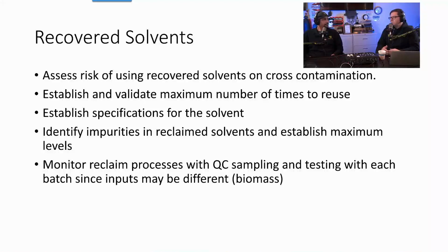The solvent reuse rules are very similar to the cleaning rules. That means you have to have a method. You have to have a validated method. You have to assess the risk of using recovered solvents on cross-contamination. You have to have a validated maximum number of times to reuse. How many people have you seen in the industry have a maximum number of times to reuse their solvents? Not very many.